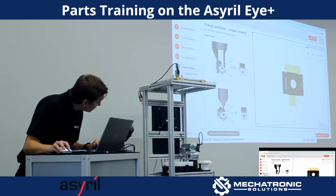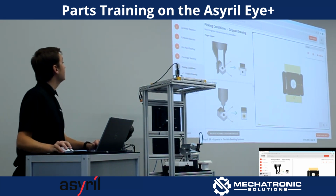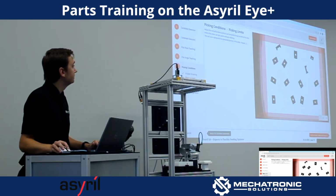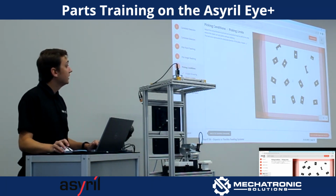So we'll just create another one right here. Again, can't see, so I don't know if these are matched up. They look good to me. You can also create picking limits and adjust picking limits here. This is, again, for gripper collisions to avoid. If that gripper exclusion zone that we just defined in this step meets with this red box here, I'll bring this in because that'll show it. It'll designate it as not pickable either.